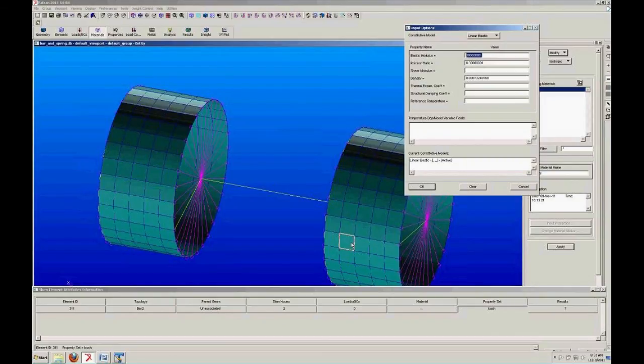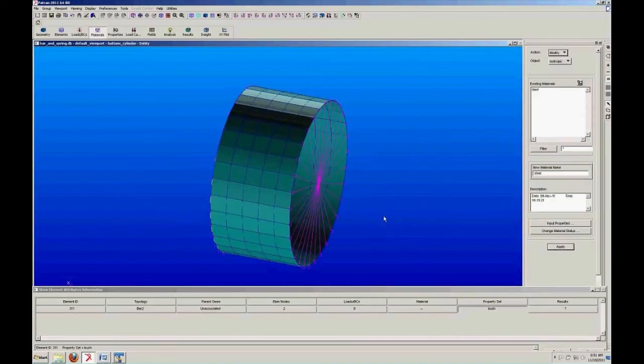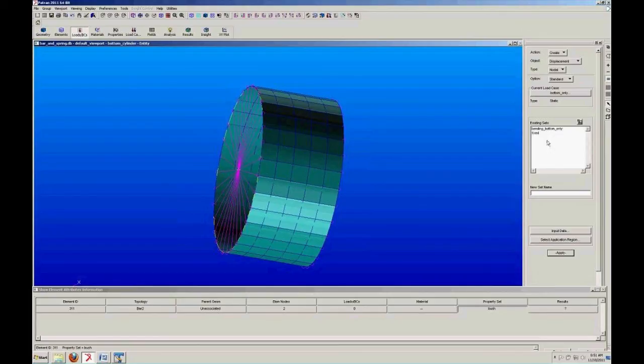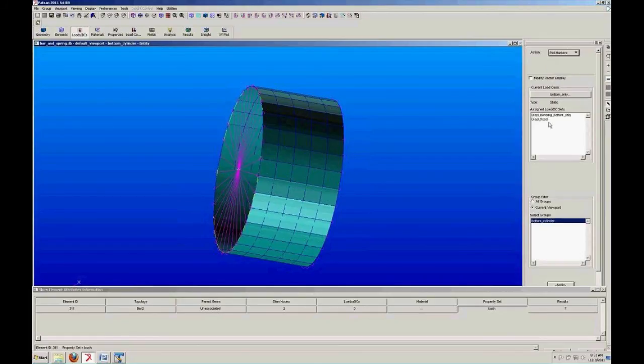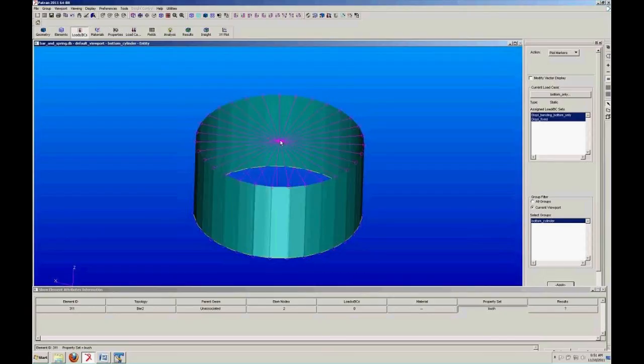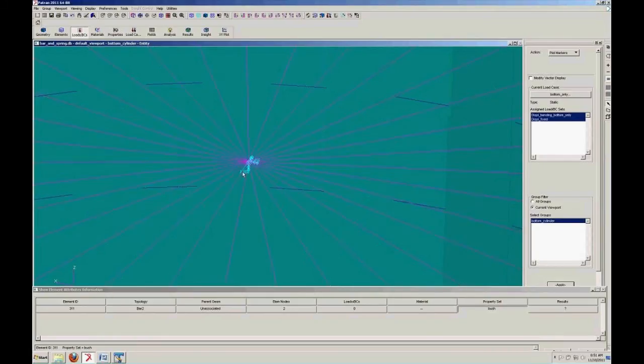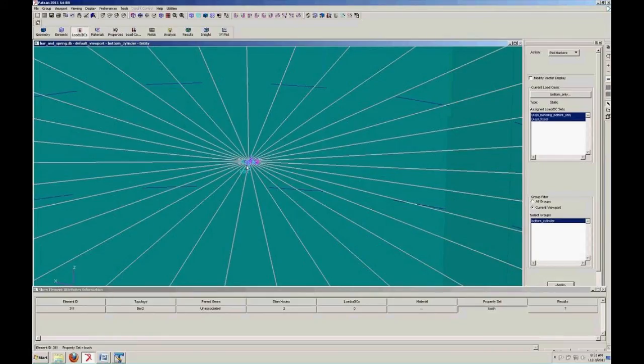If you ever want to find the stiffness, just a quick calculation for the stiffness around something, well, then in that case, what I actually did is I basically looked at one of the cylinders, and then I went ahead and put an enforced displacement. I basically put a load on here. In this case, I constrained one end, and I put an enforced displacement here, and the enforced displacement is a value of 1.0. If I zoom in, you should be able to see it a little easier. So you'll notice here, I've got an arrow here showing 1.0 and a constraint of 2, 3, 4, 5, 6.